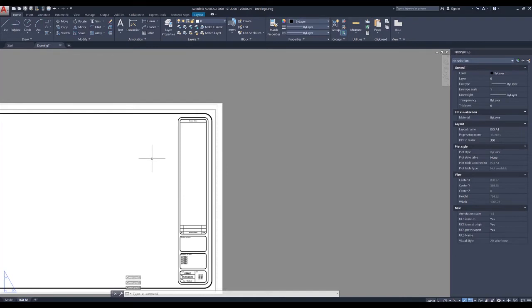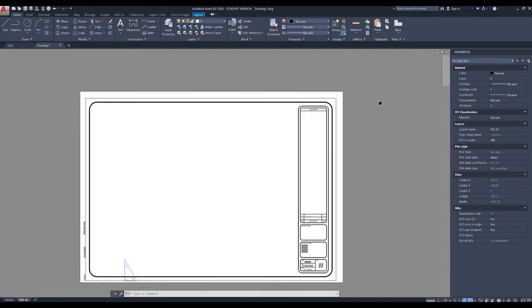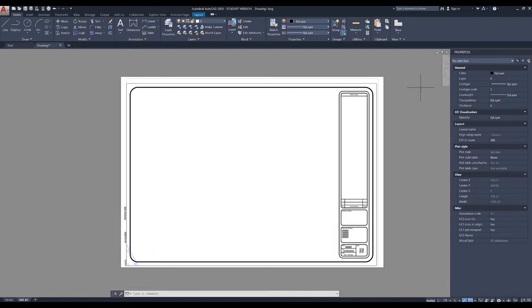And you'll come to this screen. So you'll see that there's some form of template here. There's also a properties bar on the right, and you've got these crosshairs that keep moving with your mouse. And so what you can do, if you are using a mouse, is press down the middle button and the scroll that you have on your mouse and move at the same time and hold it down, that's the pan function. So that will be really helpful as we go along.